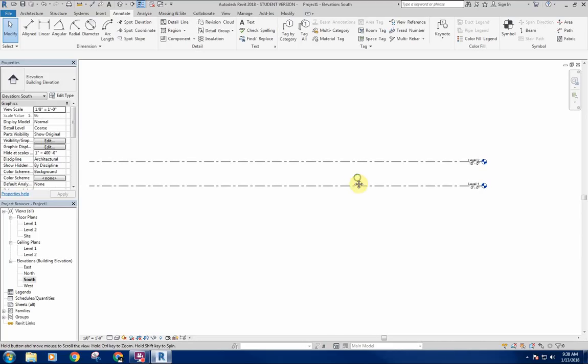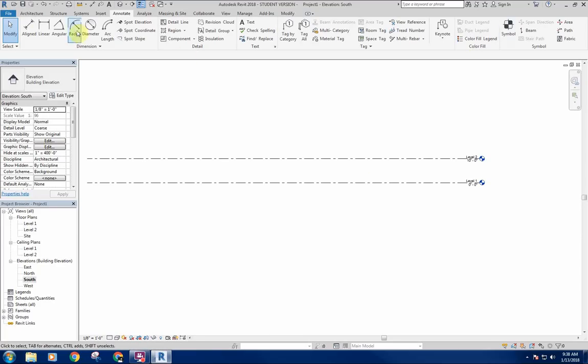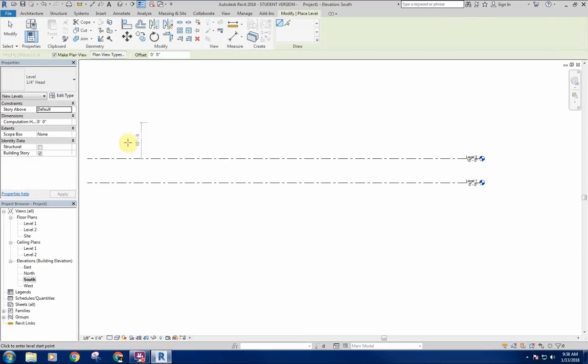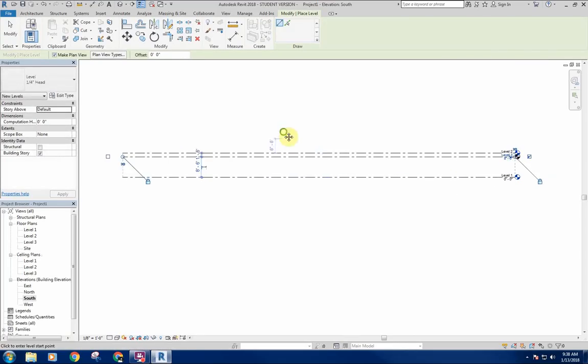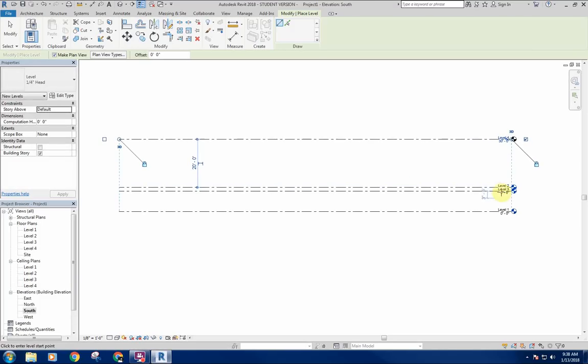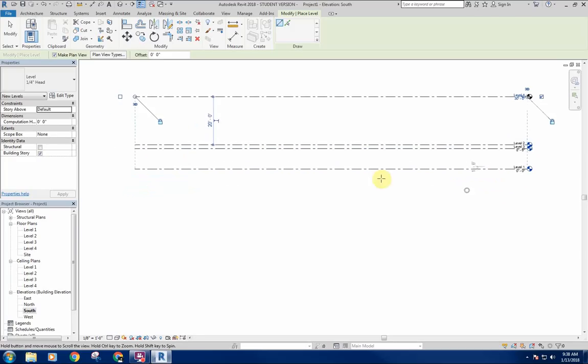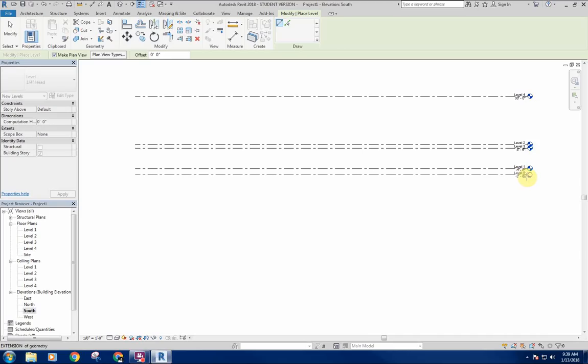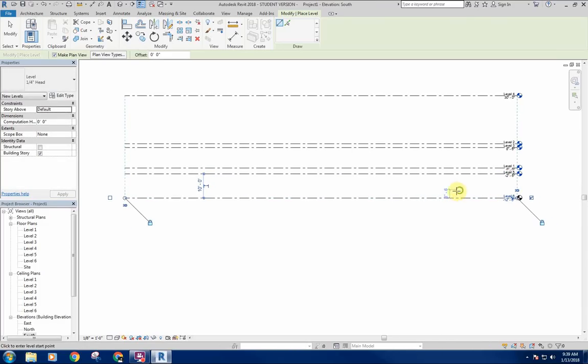So this being a small house, we're going to add a couple levels here, and then we'll figure out exactly what they end up being. So we're going to need a roof level. This one will be the ceiling level of the first floor. We will probably need, I'm going to put this on a crawl space. That way I've got a little bit of storage underneath the house. So I'll do top of foundation there, and then the top of my footer.